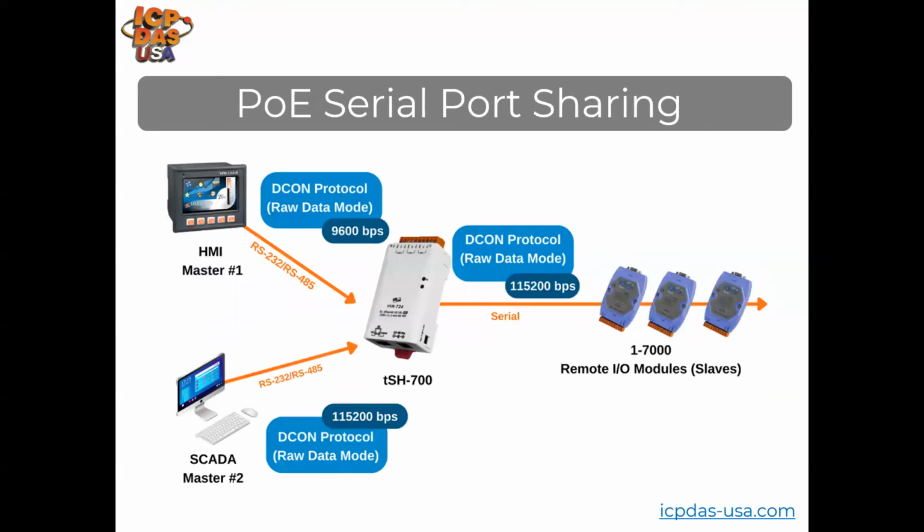They have a built-in read cache function that stores previous requests of the Modbus messages in the memory buffer. So when other HMI or SCADA master controllers require the same information from the same Modbus RTU device, the cached response is what gets returned immediately, which is why you're allowed to have two masters accessing the same slave at the same time.